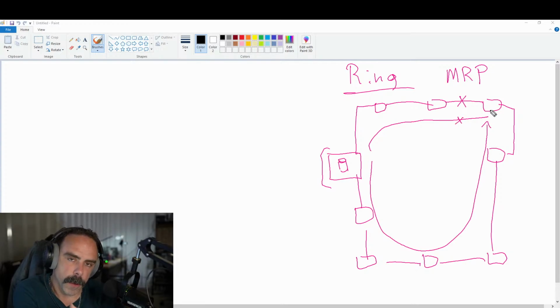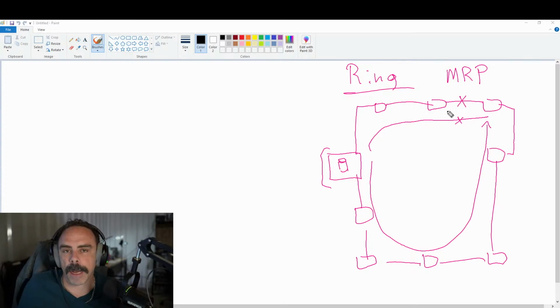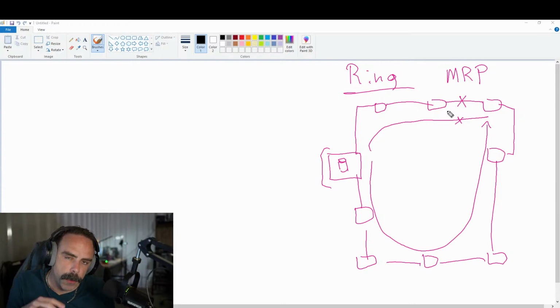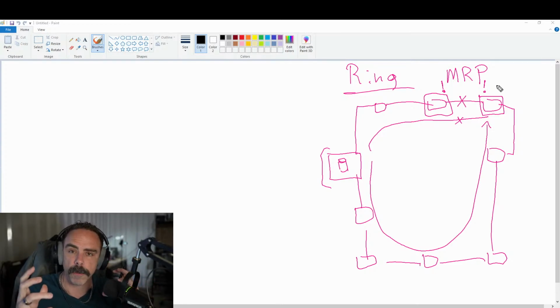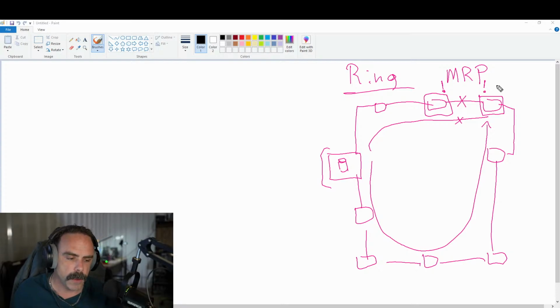So with a cable problem, an MRP ring makes it to where, hey, I don't actually lose any communication. But with some of the diagnostics that we would see later, this device would say, hey, I have a problem. This device would also say, hey, I have a problem. They wouldn't be losing any communication, and we could actually set it up to where that transition would be quick enough to where we don't even have faults on our network. But with Profinet Diagnostics that we're going to talk about in TIA Portal, these switches would report that this cable has a problem.